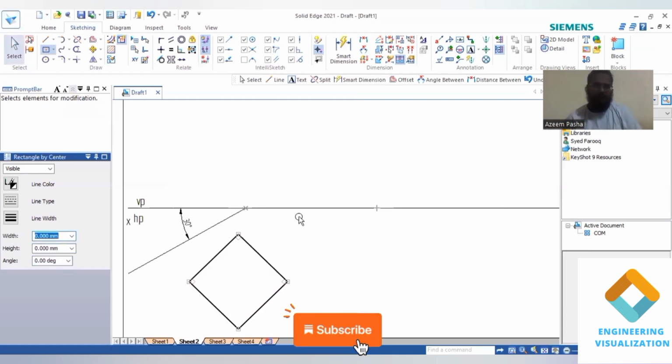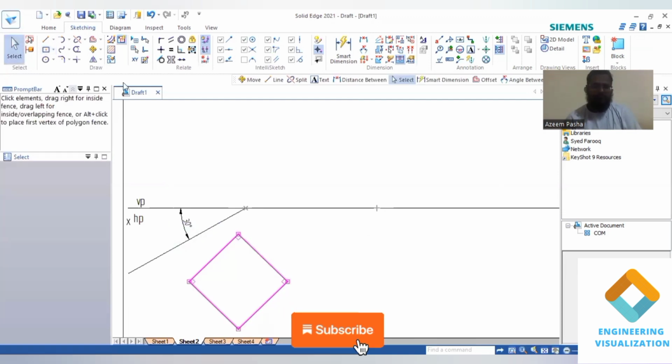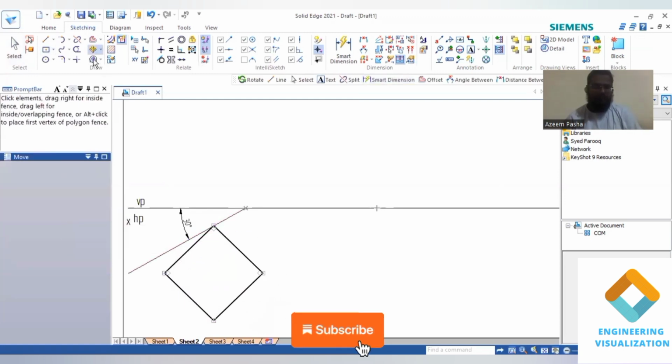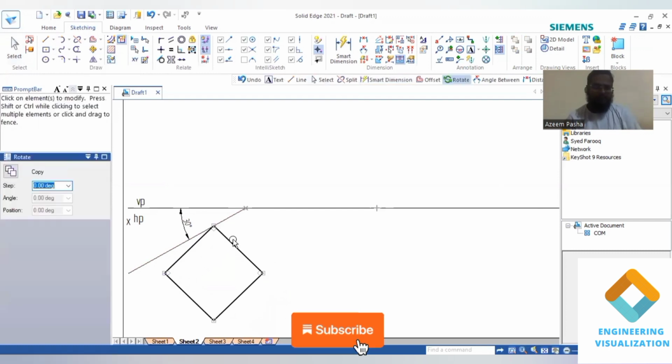When we place it on this 30-degree angle point, we select this and go to the move command, select the end point here, and place it on this angle line. Then go to rotate, and again select this whole thing, because this entire thing you have to place. Select the end point from one end to another end, and place it on the angle line.